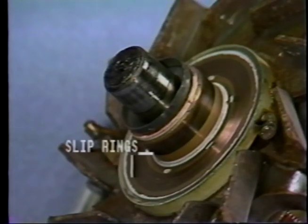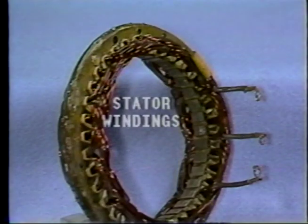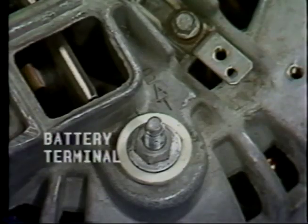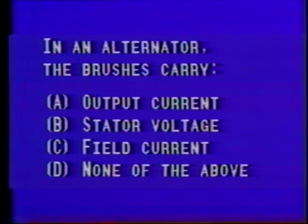The slip rings, therefore, only carry relatively low amperage field current. Electrical output from the stator windings, once rectified by the diodes in the rectifier bridge, is the high amperage output current which is measured at the battery terminal of the alternator. So the correct answer to this question is response C, field current.